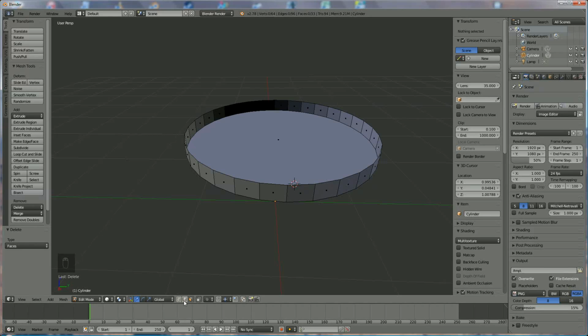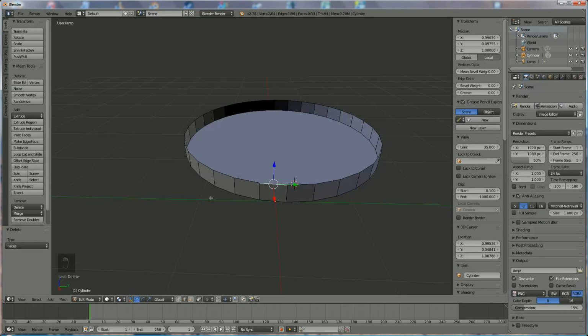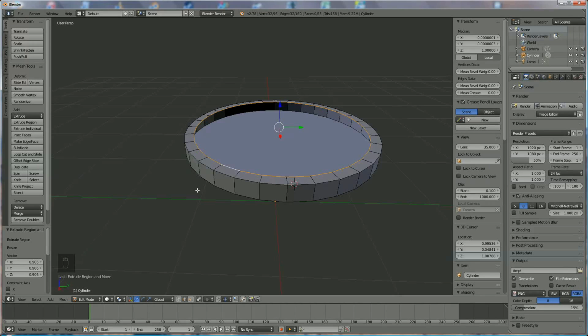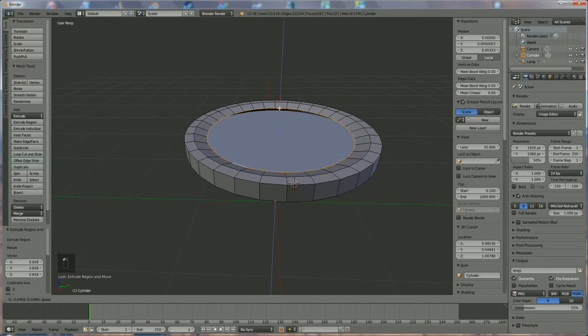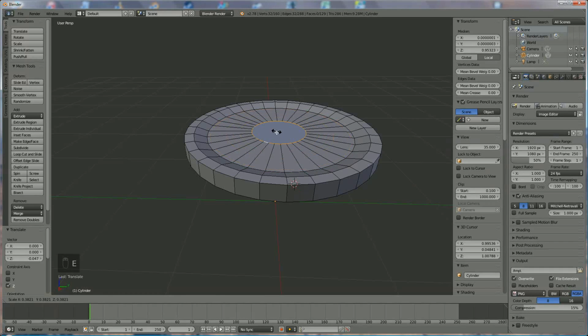We're going to use edge selection. We right click on that edge, hold down the alt button and right click on the other edge. Press E, extrude, press S to extrude to the center and bring it to the center through something like this. Going to repeat it by pressing ES again, left click with the mouse, and now bring it down a little bit.